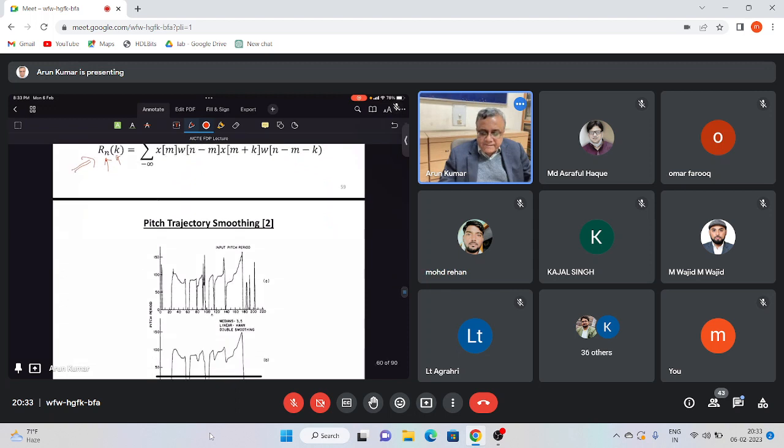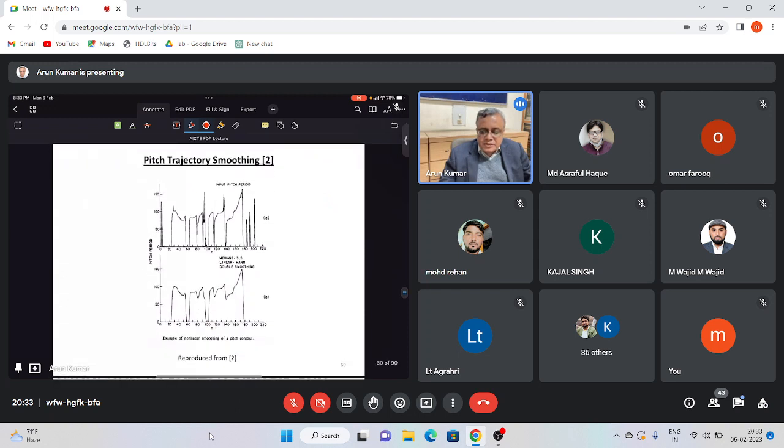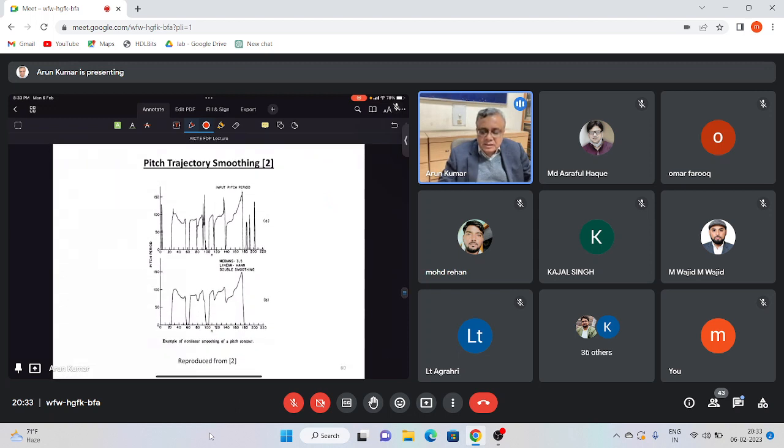And now, a basic application of this method generally leads to errors, because sometimes the peak at twice the pitch period, that is 2P, may be higher than the peak at the pitch period P. In which case you would wrongly estimate the pitch period to be double that of the true pitch period.